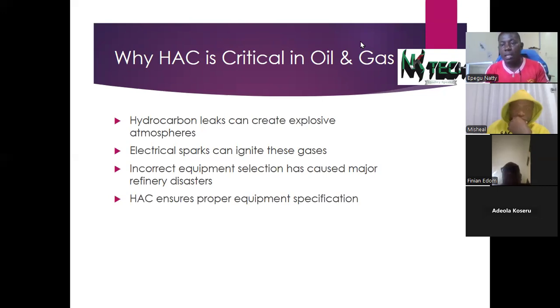So if a pump is operating at a temperature of, let's say, 40 degrees, and we have a gas that is going to vaporize at a temperature of, let's say, 50 degrees, it means that place is safe due to the selection of that equipment. But what if you bring in equipment that when it's working is going to get hot to a temperature of about 60 degrees? Meanwhile, you have a gas that can ignite at 50 degrees. What's going to happen? There's going to be an explosion whenever there is a leak of that particular gas.